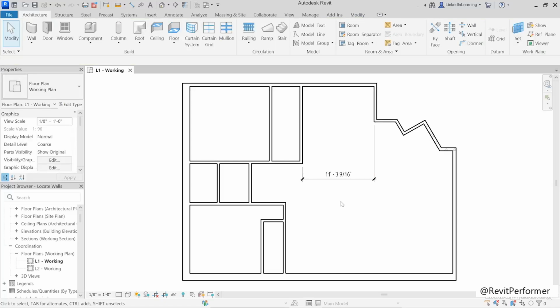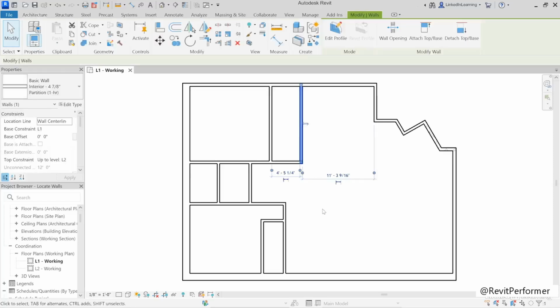If you click that, notice the tooltip says it's going to make that temporary dimension permanent. And if I click away from that wall, I now have a dimension there. Now that's useful, and in some cases that may be what you want, but that's not what we want right here. So I'm going to select this dimension, press the delete key, and then try again. I'm going to pick this wall, and what I want to do instead is click right on that numerical value. That will activate it as a piece of editable text, and now I will type in the value I want. Now, if you're working in the imperial file, you want 8 foot 1 inches, and again, you can either do 8 foot symbol 1 or 8 space 1. If you're working in the metric file, put in 2575, 2,575 millimeters. Notice that that will move the wall over to the right.